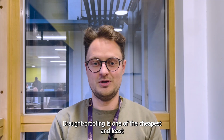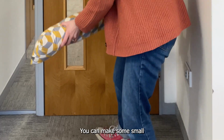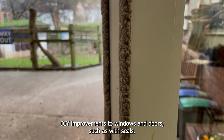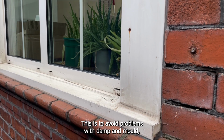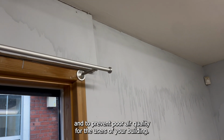Draught-proofing is one of the cheapest and least disruptive ways to improve the energy efficiency of your building. You can make some small DIY improvements to windows and doors, such as with seals. Make sure there is adequate ventilation if you do this. This is to avoid problems with damp and mould and to prevent poor air quality for the users of your building.